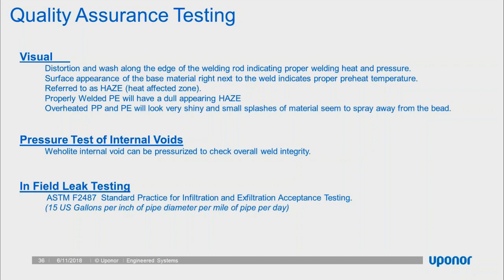Exfil is typically a 24-hour drawdown where they'll fill the structure with water and then observe drawdown time over a 24-hour period of time. Infiltration testing is they'll leave the structure empty under groundwater pressure from the exterior of the structure and observe how much water gets into the structure.